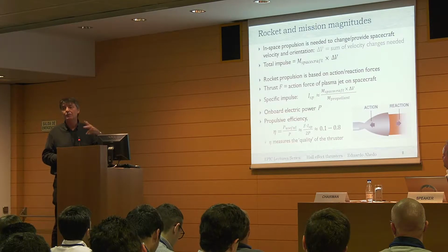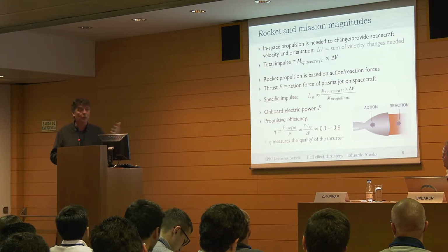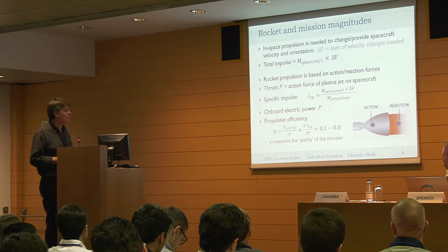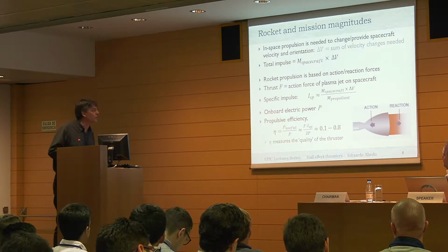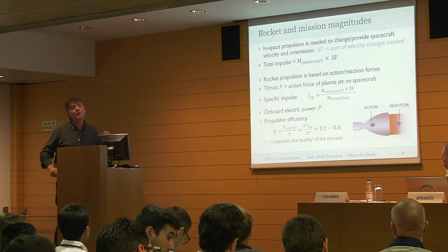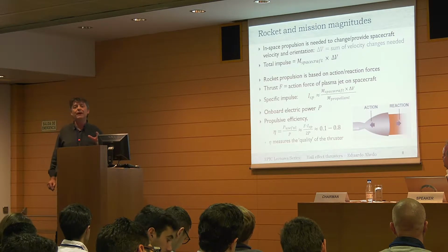So we have already talked about the specific impulse. We talk about the quality of the thruster through this. Then there is lifetime. We have talked a lot about lifetime, how long the thruster is going to be useful, to be operational. And another parameter that is more difficult to quantify is the simplicity of the thruster, how easy it is to operate the thruster, okay? And this is very important. For instance, this morning they also talked about this LEO constellation, and there we want more compact thrusters, cheaper thrusters, and then we want simple thrusters, okay?